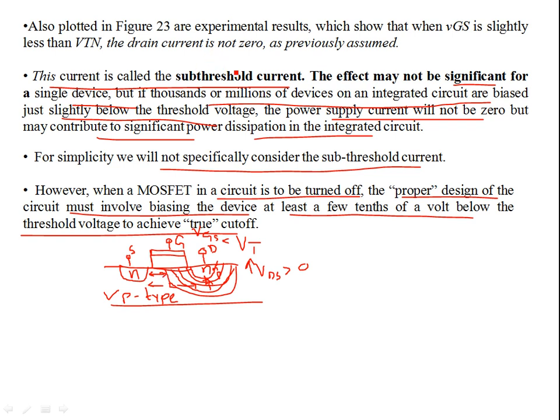This leakage current, physically, we call a sub-threshold current, and due to this you will see a leakage conduction even below the threshold voltage of the gate VGS. Even if VGS is less than VT, the barrier is lowered. This phenomenon is famous as drain induced barrier lowering in MOSFET, DIBL.